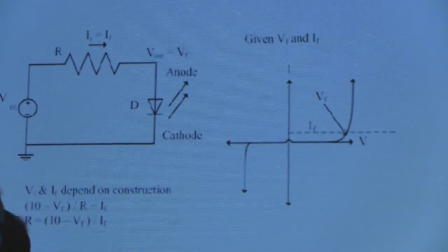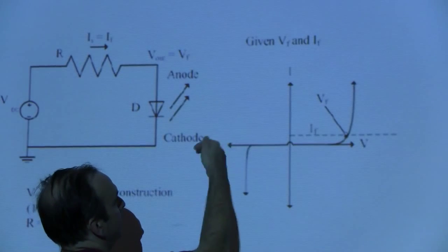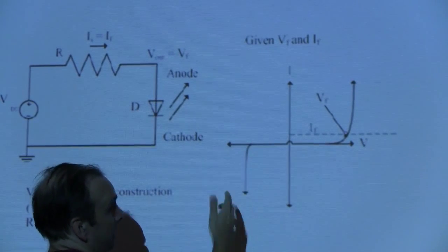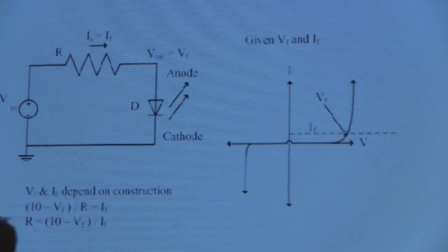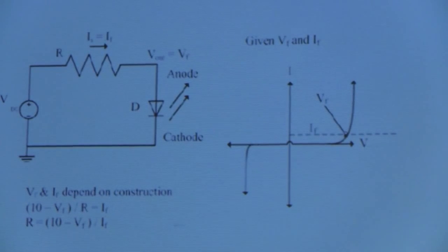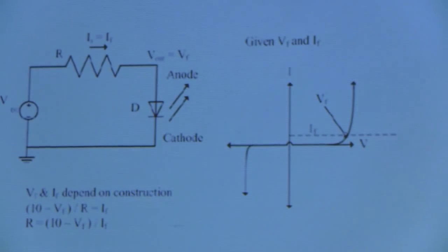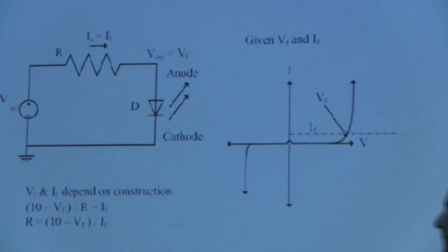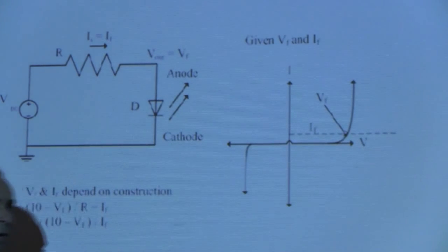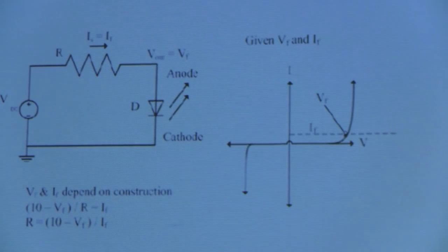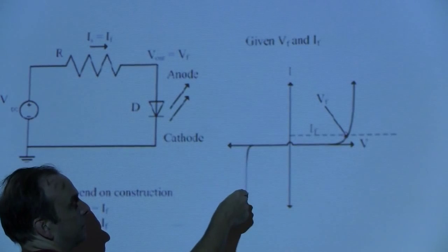So if I apply a voltage that is more negative than this, it in effect clamps the current. It's because the shape is a more sharp turn than forward. Right, a sharper knee. The knee is very precise, and it's precisely positioned in manufacturing. Where they put that slope, farther out or farther in on the voltage axis, is how they make the Zener voltages. You buy a Zener, it's a 6-volt Zener or a 12-volt Zener or a 100-volt Zener.